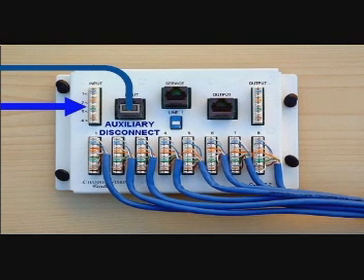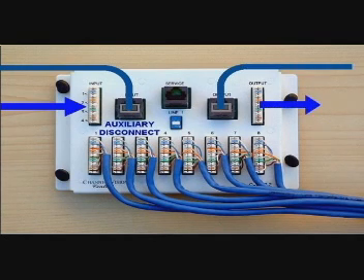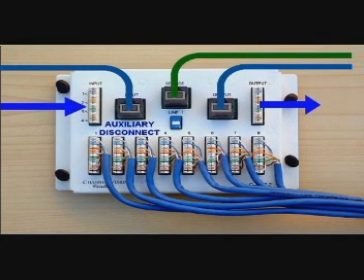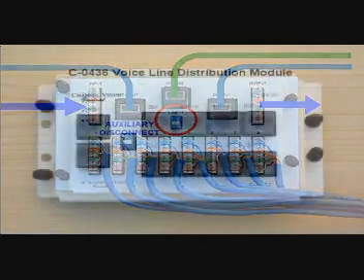If more than 8 voice outlets are needed, additional modules can be added as necessary by using a jumper cable from the output jack or punch-down connector. There is also a jack on the module to allow connection to a security system. When the line 1 switch is in the up position, line 1 is routed through a 4-pair cable to the RJ31 jack on the security system. This allows the security system auto dialer to seize line 1.